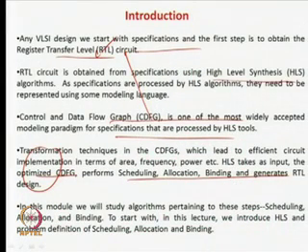So, we take a CDFG which comes as the input from the specification, then we go for the pre-processing step, where we optimize it, and then we go for scheduling, allocation and binding problem, which generates the RTL design, or in other words your architectural level block level design. So, that is the idea of high level synthesis.